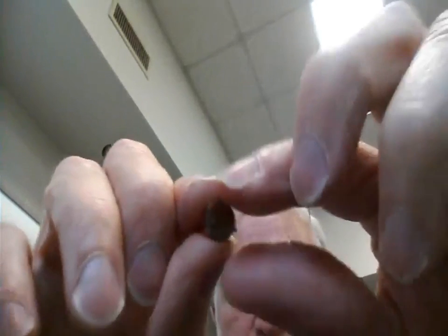These guys are real neat because notice the leads are in a V, right? And we got a little tab, by the way. The tab identifies the emitter. And usually this guy here that's offset is the what? Is the base. And then the collector is real easy to see. And of course, the bigger the package, the more current IC, and the more power it can dissipate. This is a TO-92. These are the ones that we're going to be using.